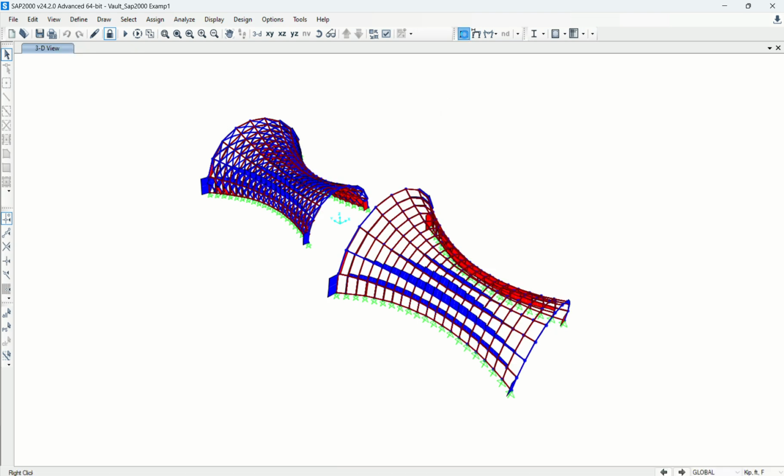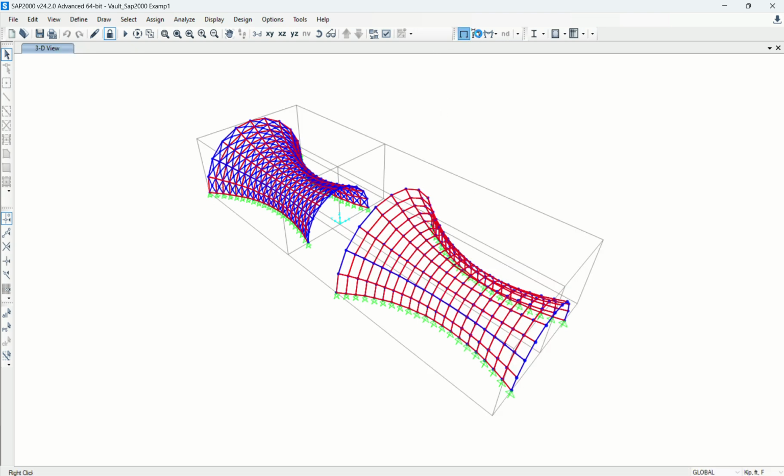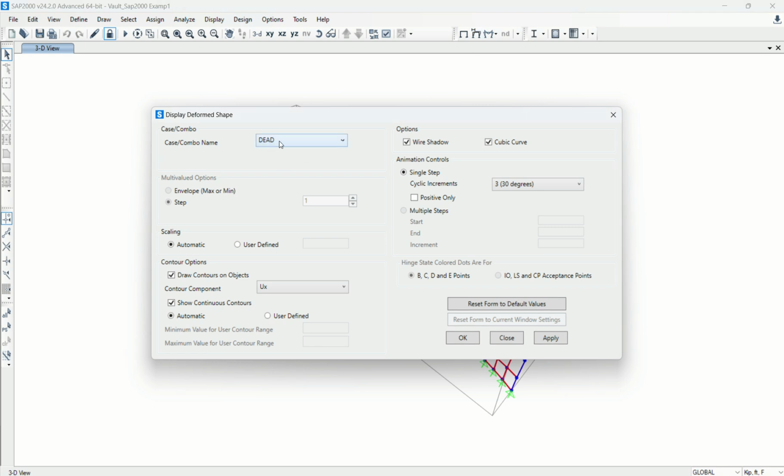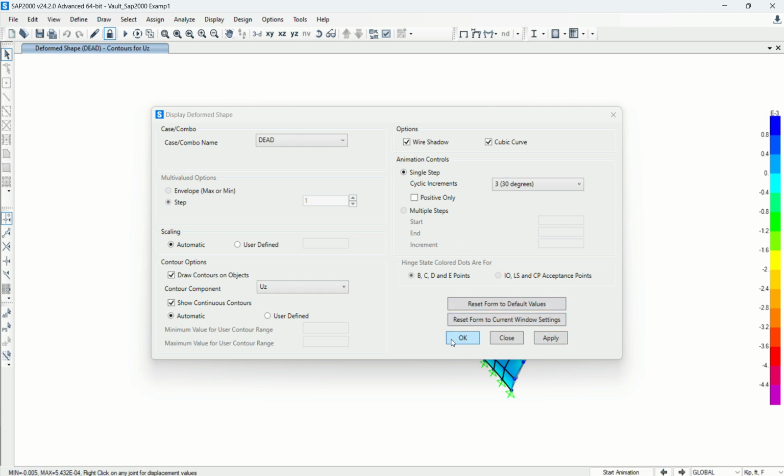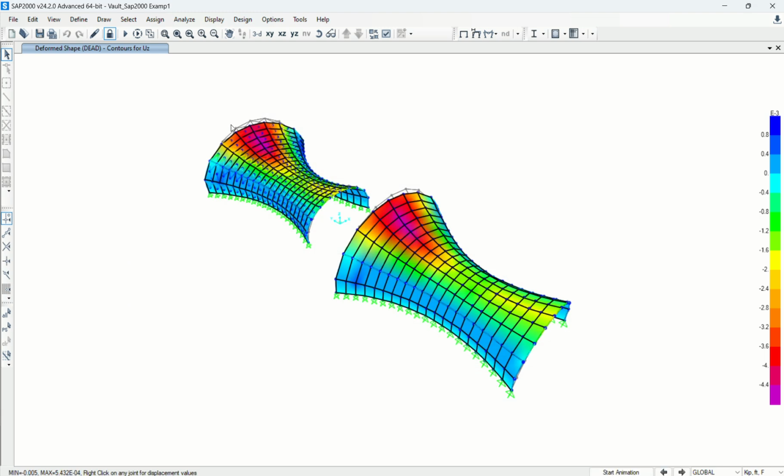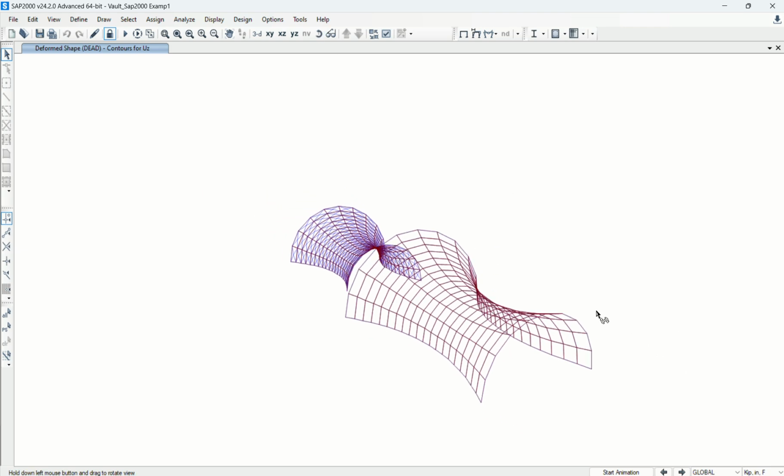Okay. Oh, it showed some results. I'm going to show you deformation first. Self-weight deflection, and obviously vertical Z deformation. I'm going to turn off. Let me see. Okay, it shows some color coding. And this time for deflection, I'm going to use inches. So you see that the deflection is 0.053. Oh, this is self-weight deflection, so probably small.